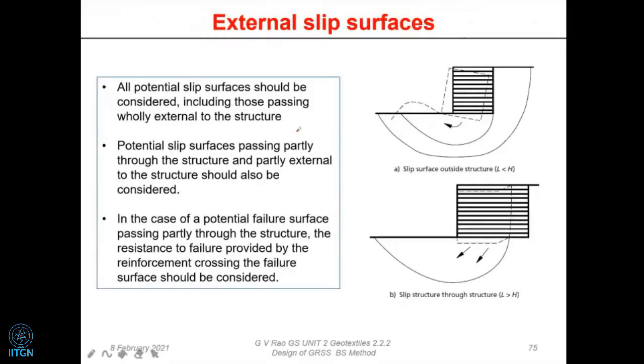Then we are talking about the global stability. So earlier in the sketch I have shown you, global stability meant the wall, of course, is tilting. Global stability is there now. But in this case, we have to do more than that actually. See, one kind of global failure situation we are going to get is like this. That means it's failing like any other wall. Now if the soil here at the bottom is rigid or stiff, this is a horizontal plane. It's not really giving elliptic or log spiral or something like that.